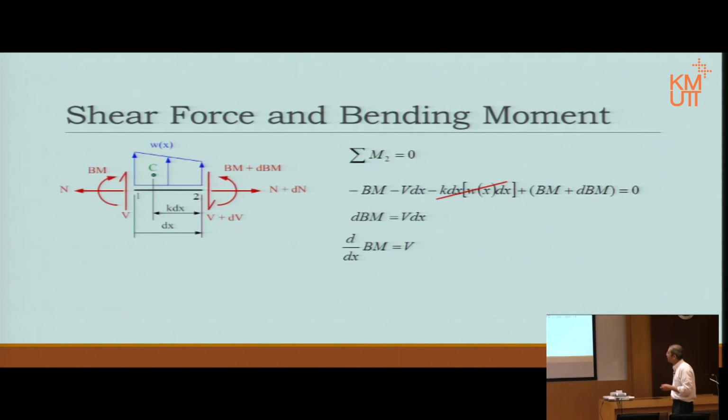The first interpretation is the differential interpretation. That means differentiating the bending moment is equal to shear, basically. Now, that has a significance because when you differentiate the bending moment, or any function with a variable, in this case the bending moment is a function of x, right? We already found so many equations and functions with that. We know the bending moment is a function of x.